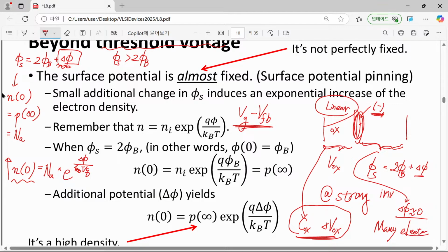That's the reason why when we additionally introduce delta Vg into our gate voltage, almost all delta Vg is assigned to delta V ox, because these two different mechanisms, one oxide charge and one silicon charge, should describe the same behavior, the charge collected underneath the oxide layer.